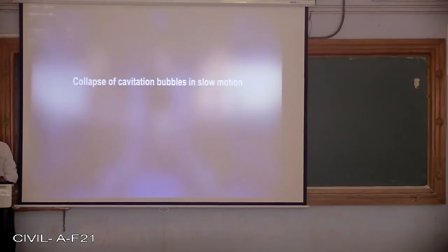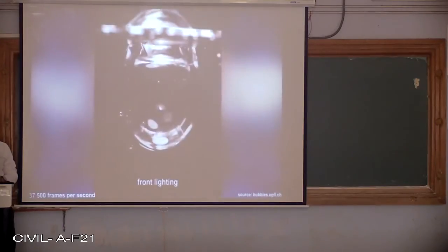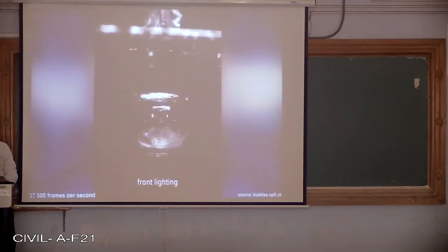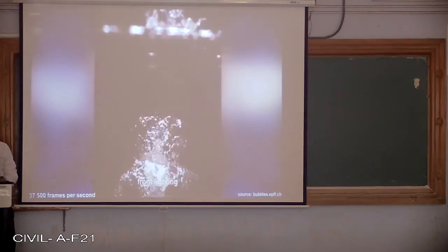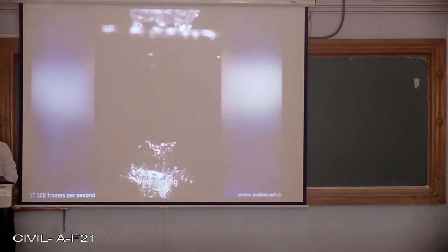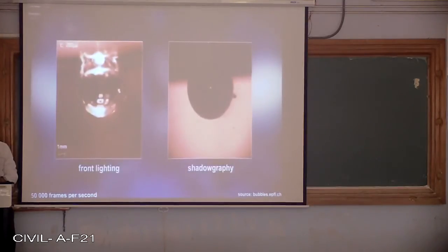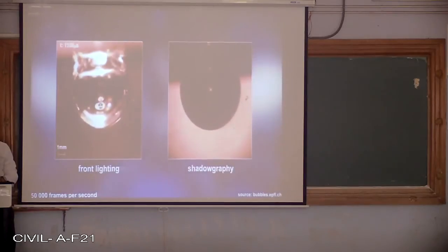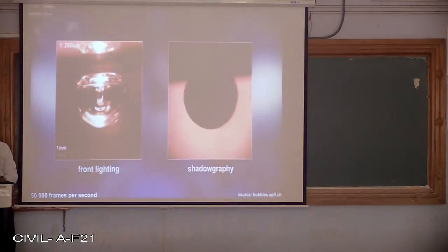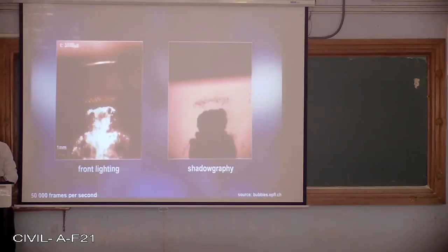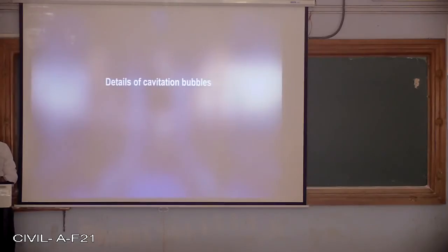But how does it look when cavitation bubbles are formed and collapse in detail? We can see the formation and the collapse of cavitation bubbles with a diameter of approximately 9 millimeters in slow motion. In real time, this process takes about 4 milliseconds, and it is a spectacular physical event. Because liquid water occupies many thousand times less volume than vapor, the bubble implodes. It first assumes a ring shape. Shock waves and a strong microjet are the result of a collapse. Let's go through the whole process again.